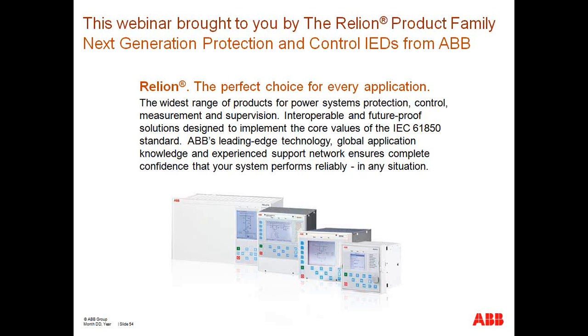And really, the considerations are not different. The security concerns are no different than with any other communication protocol, such as Modbus and DNP. 61850 does provide, within its framework, enhanced and further layers of security to validate who's sending particular commands and so on. But to answer your question directly, GOOSE messages are part of a non-routable protocol, and a GOOSE message lies on layer 2 of the OSI model, so it technically cannot go from one IP network onto another.